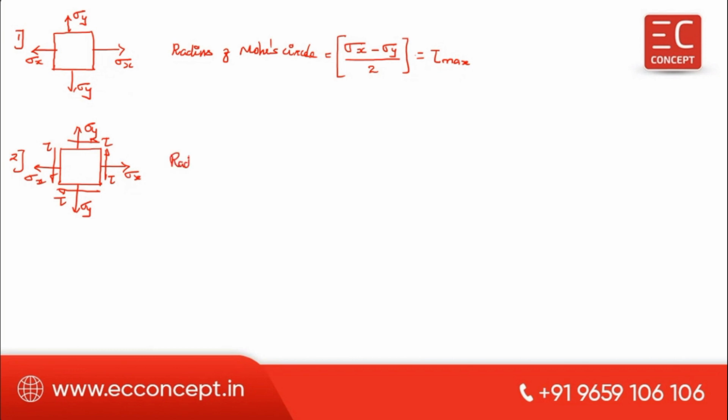Now in this case, the radius of the Mohr circle is equal to the square root of ((sigma x minus sigma y) divided by 2) the whole squared plus tau squared. This is also called the maximum shear stress, tau maximum.